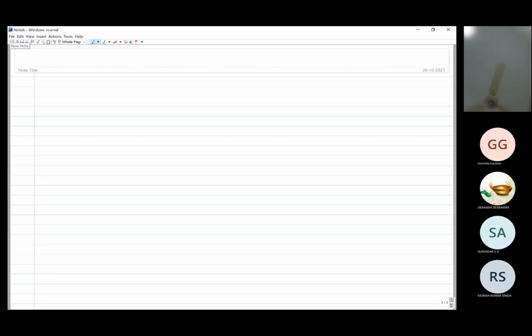Now, as far as the parameters are concerned, let us talk a little bit about the joint design first. What you have to consider is the kind of loading that will be there, and another important thing considered in adhesive joining is the plastic strain capacity or capability of the adhesives.